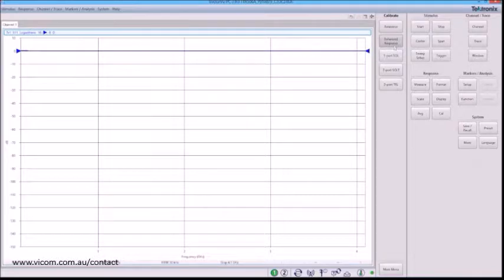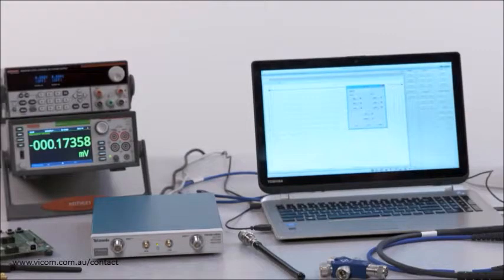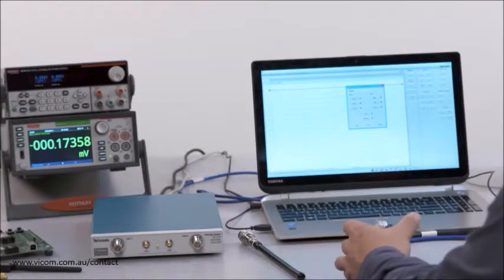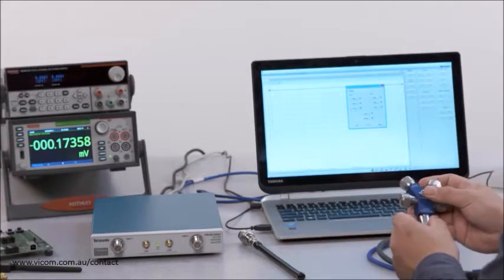and depending on the type of calibration that you'd like to do, if you want to do a single one-port cal, you would click on one port SOL. In our case, we're going to do a two-port cal, or a two-port SOLT cal. So we click on that. And this little sub-menu pops up.